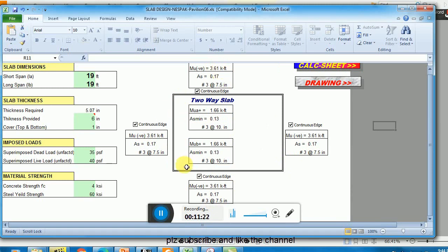You see that in a square panel, basically this is critical analysis, the loading distribution on all beams is the same, but when you are dealing with a rectangular panel, you have to watch the longer span beam, because to the larger side of the beam maximum load is transferring. So this is the way.